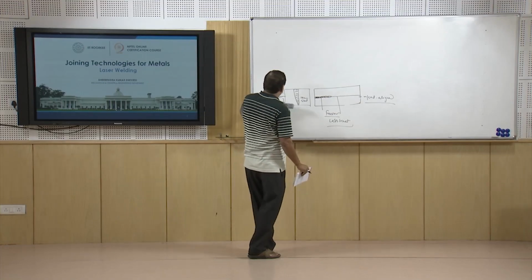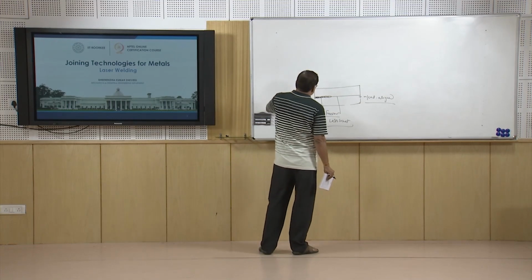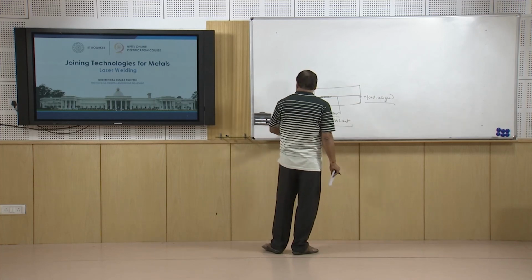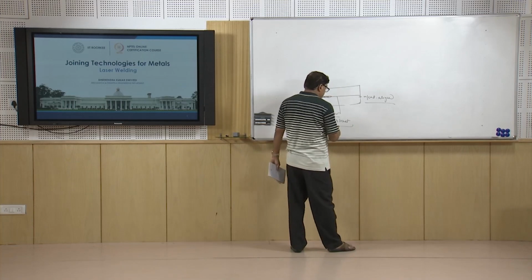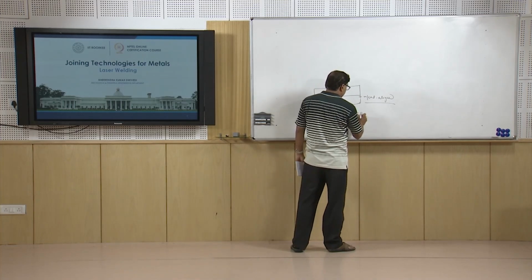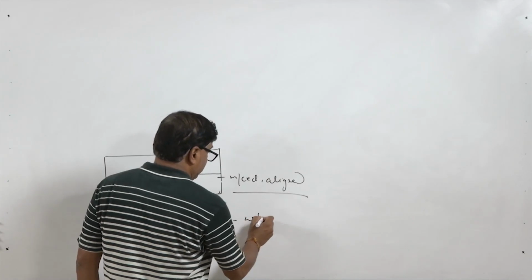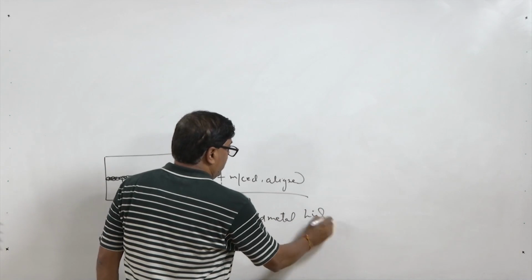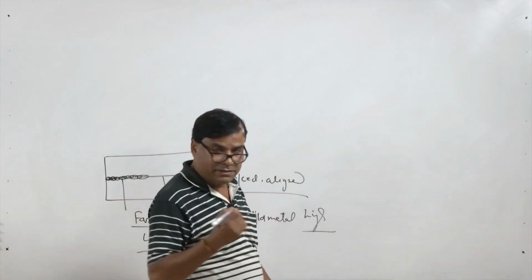Plates up to 19 mm thickness have been welded in a single pass. Since the process works very fast, it melts very fast and uses very little heat input. So, the cooling rate experienced by the weld metal is very high. High cooling rate results in certain favorable things and unfavorable things also.